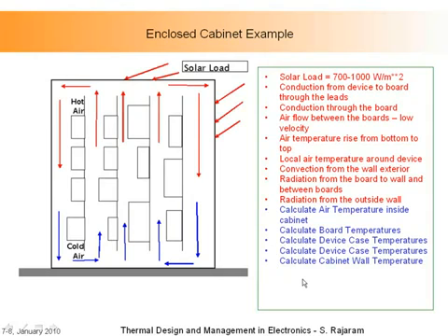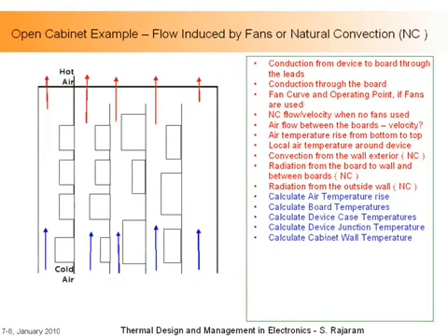We do CAD modeling and measurements to do this. So there are limits to what you can do with a completely sealed cabinet. Now, in the open cabinet, like the shelf I told you, there you're allowed to use fans to pump air continuously through. The problem is very similar, except that the fan can pump air, pick up heat, and go outside. And once again, we do the same things. We take the information that's provided, and then we calculate these parameters that are shown here.